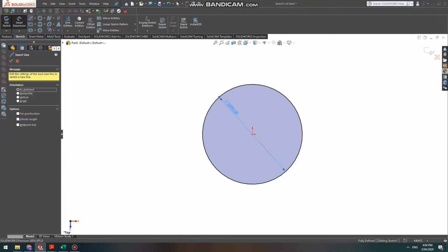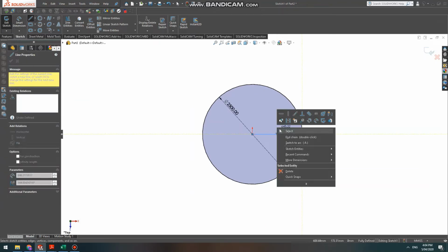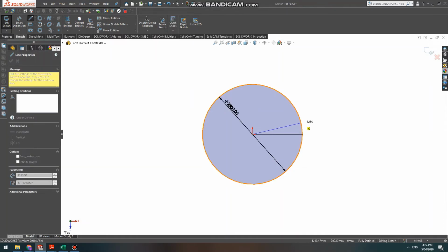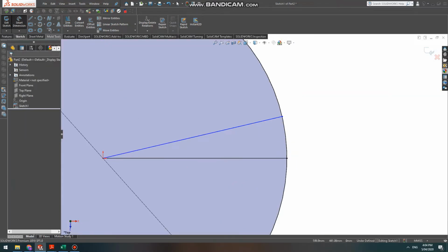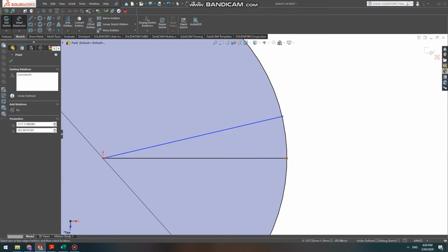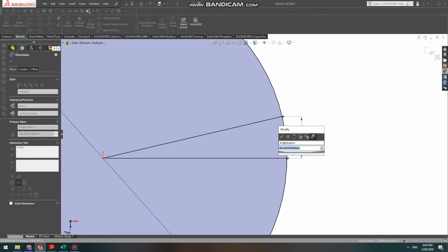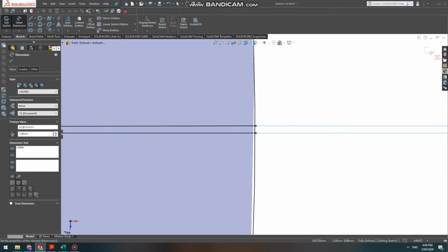and we have to put a cut place on it, because when you bend it, you bend a sheet, and when you bend a sheet, there will be a part which will stay not connected. So that part we will weld, so it will undergo welding, and by standard it's around 3 millimeters.